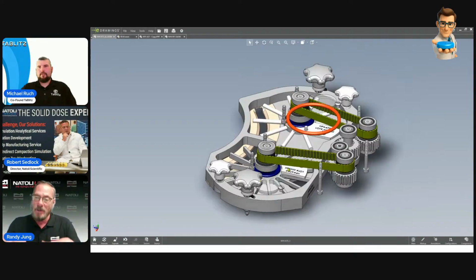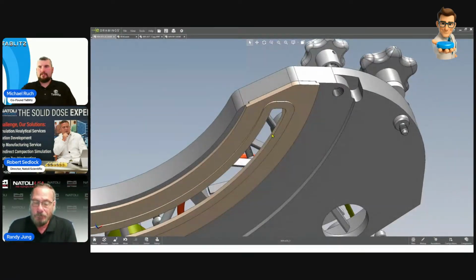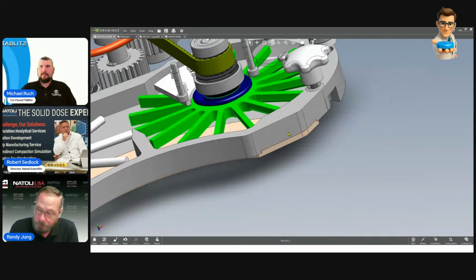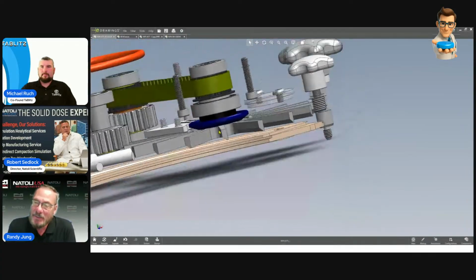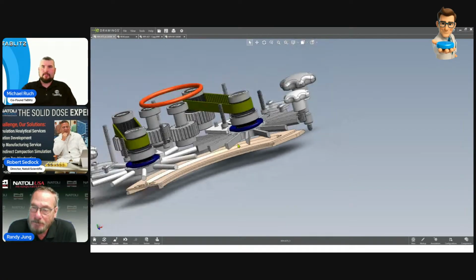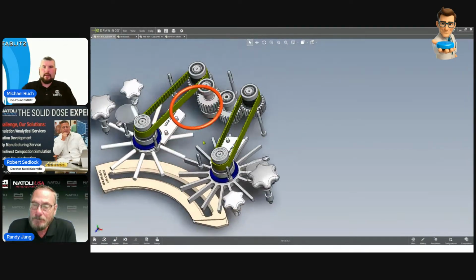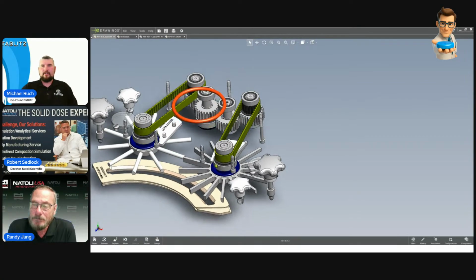For those of you who are trying to understand what the plow design is, what Randy's explaining here, you'll see there's a chamfer on the edge of this paddle. It's hard to see here, but maybe if I hide the body here, you'll see that this paddle actually has a chamfer on it, and it spins clockwise the way we're looking at it here, and so it's actually pushing the powder into the die. That's what we're calling the plow design. And then this one here is the wire. And the other one that we had shown was just the standard.